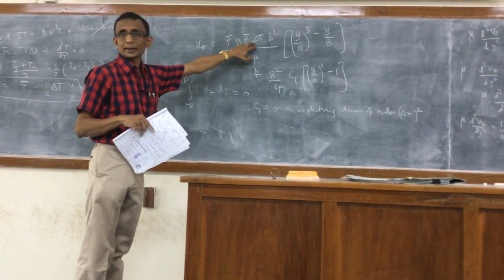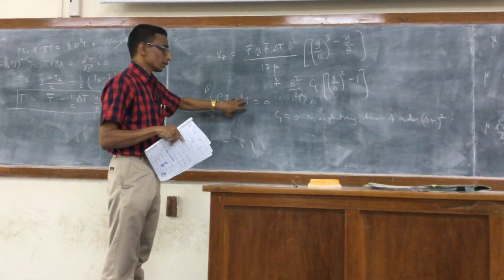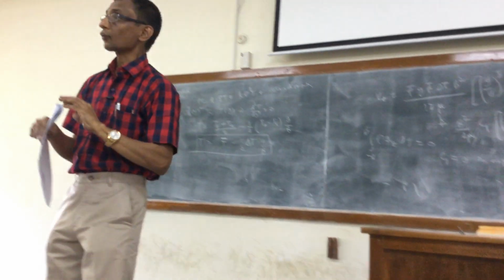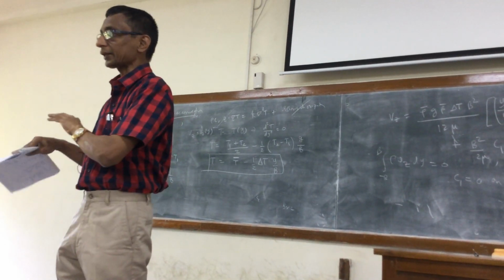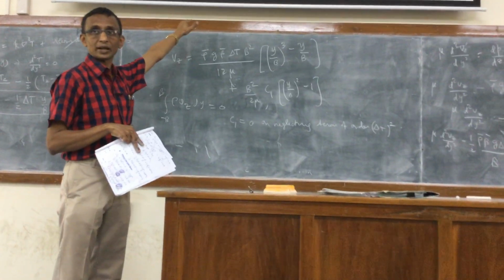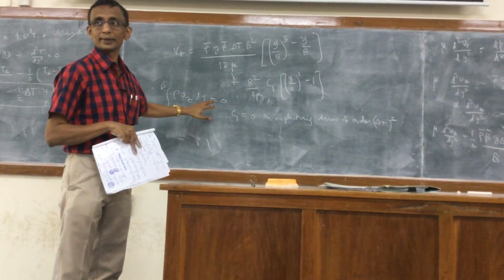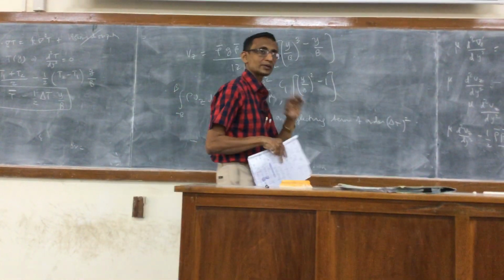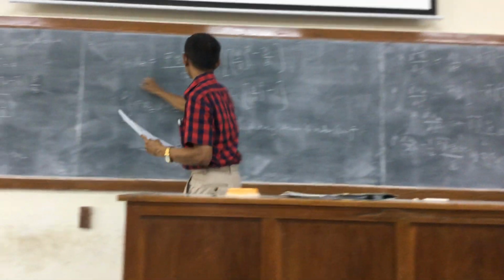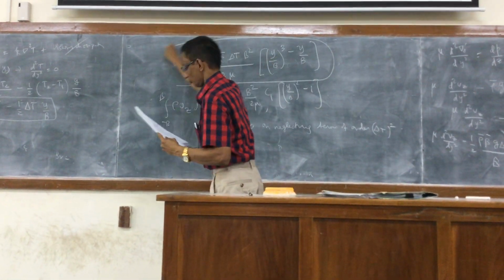Ez also has a delta T here. So you get terms of the order of delta T squared. If you neglect them, which he says is consistent with the Boussinesq approximation, because there we have neglected them, you will find that C1 would simply become equal to 0, and all you would be left with is this profile.